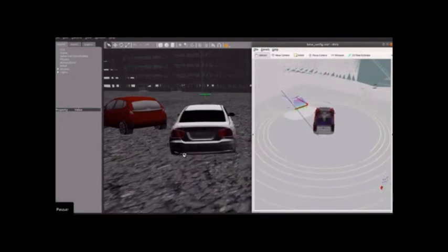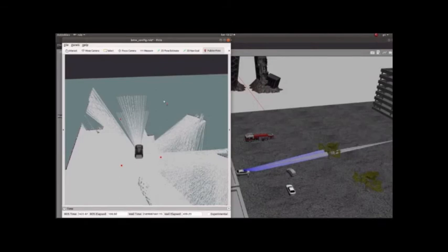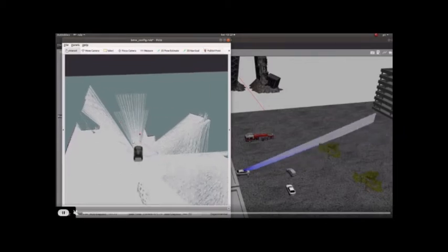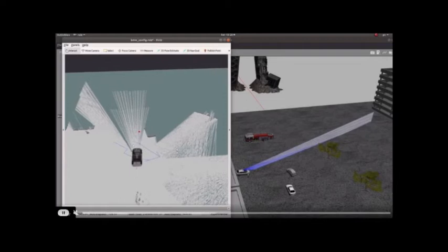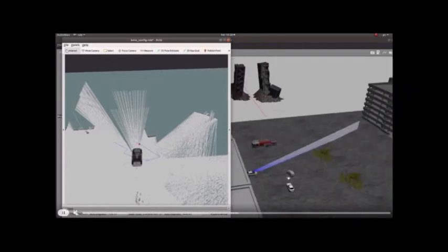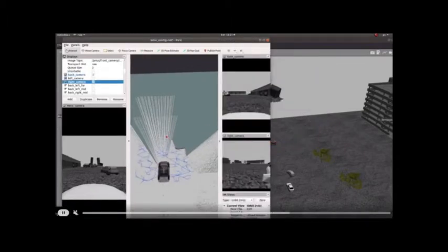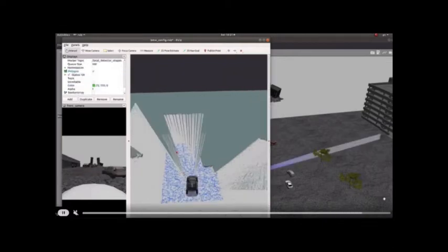Okay, again, this is the same video, and the last one I tested was the rapidly exploring random tree, to check if it found the goal. The RRT starts exploring the area, and then this is the final tree. As you can check, it's random, and this is the final path in red. Now it's the tree expansion.